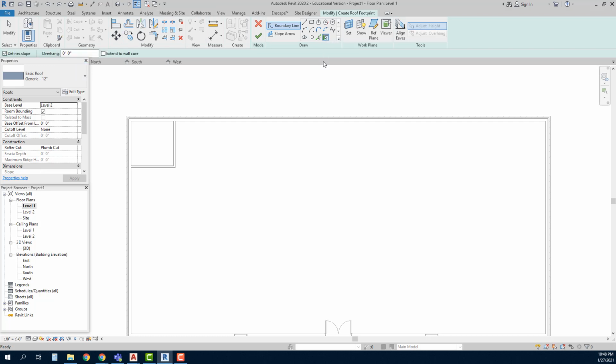Now if I go back to my pick tool and I pick my wall, you'll see it's giving me a dashed line when I pick this side of the wall. If I pick this side of the wall, it gives me a dashed line. So that's showing me where my overhang is. I definitely don't want my overhang on the inside, so I'm going to pick out here.